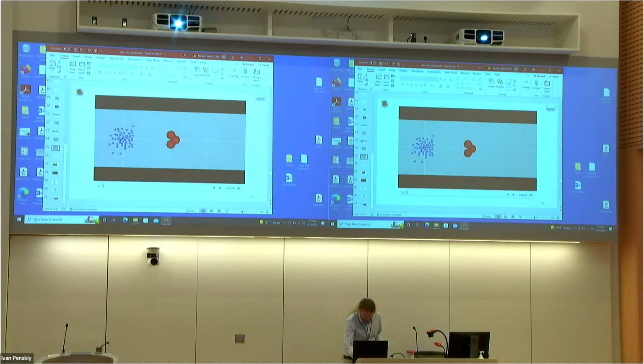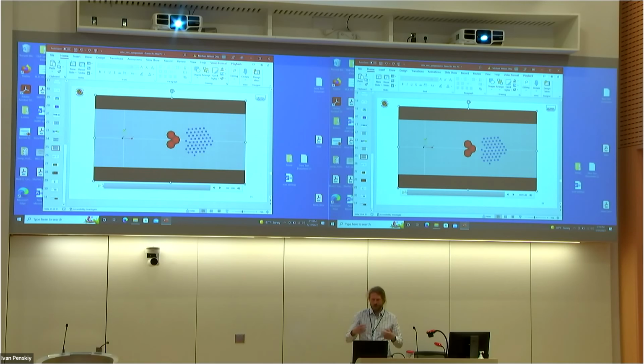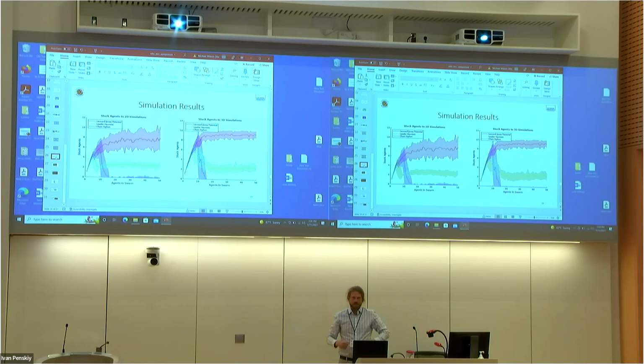More robots on this slide. In this case, there are so many robots that they can go both directions around, and the goal is reached in two independent ways. In the previous one there weren't as many robots, so the robots that went over the top found the goal first and siphoned the rest of the robots around to the other side. We compared to Lennard-Jones potential algorithm and also a leader heuristic, and we see that if we have enough robots, then we can successfully get around the local minima.